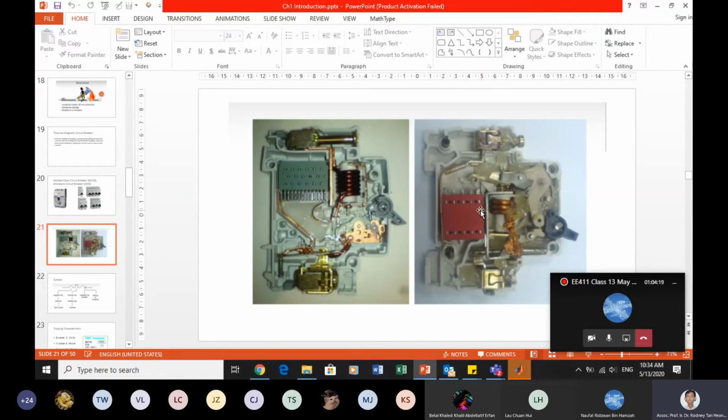And the arc chute, you see the arc chute, the metal plates here. You see in between there are empty spaces, and you see this one, every slot is actually full with metal plates. Okay, so how to distinguish counterfeit? Of course, you cannot open it. Very simple. You take an original branded one, Schneider for example, and you buy another Schneider counterfeit. On the outside, they look exactly the same. To distinguish, you hold one in each hand, two hands, and you feel the weight. The heavier one will be the original one because they have much better materials inside.